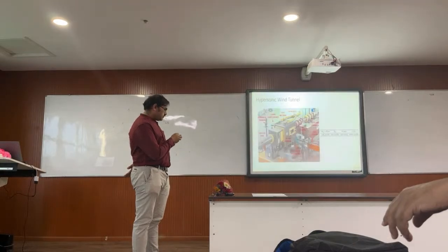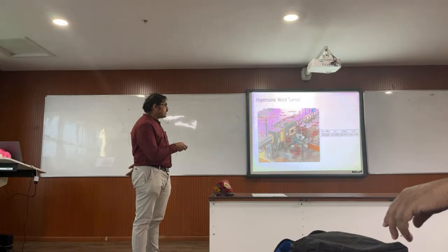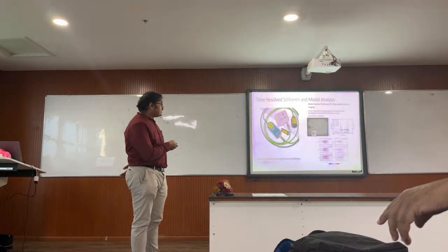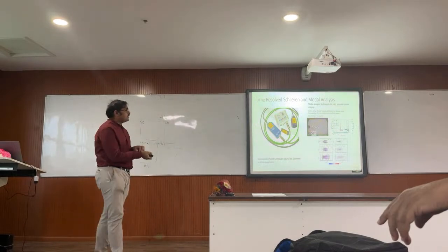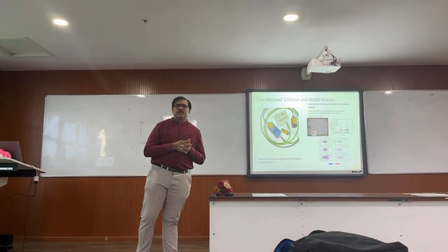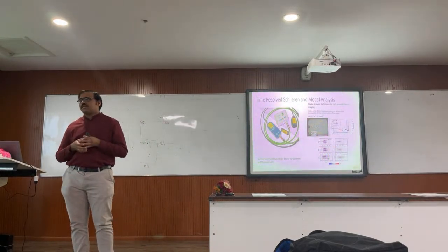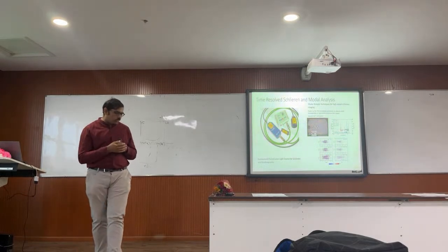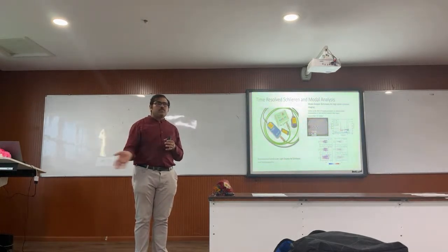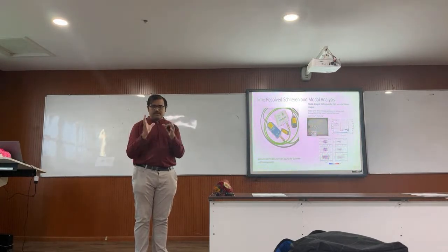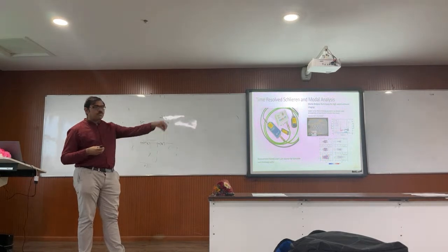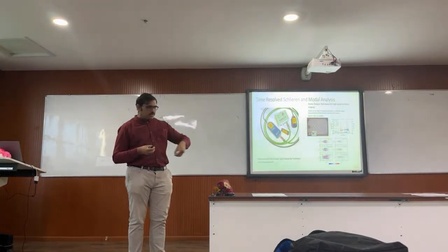So basically we use Z-type schlieren. I hope Z-type schlieren has been explained to all of you. And what we wanted here is to study the unsteady aspect of these flows. So that means we need to sort of freeze the flow. Otherwise, while capturing the flow, if there is something moving, you can see, if you try to photograph a road in a dark night, you will see all lights streaking. Why? Because you have moving cars and they are moving at a speed much faster than your shutter speed. Therefore, the exposure is very large. Within the exposure, the object has moved, and as a consequence, you get what is called motion blurring.